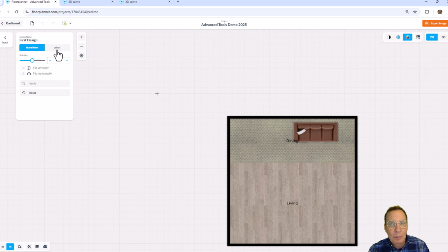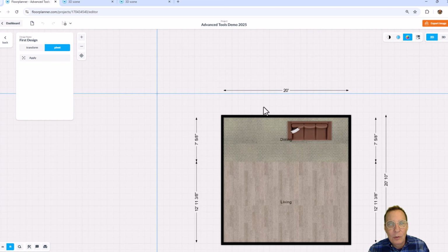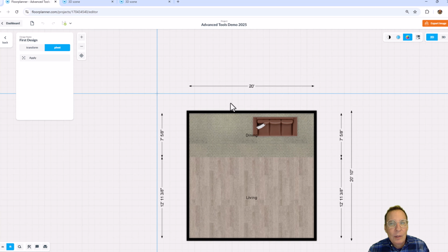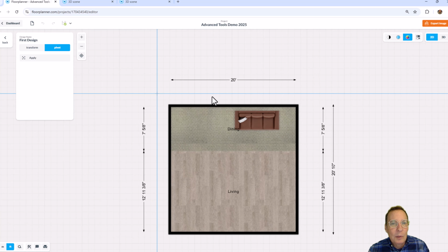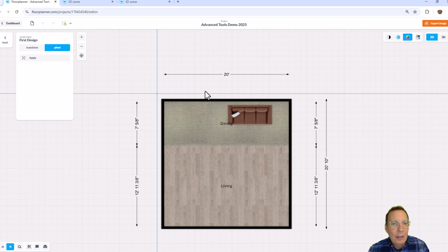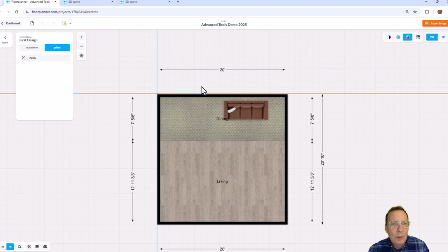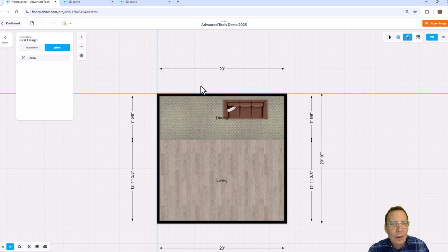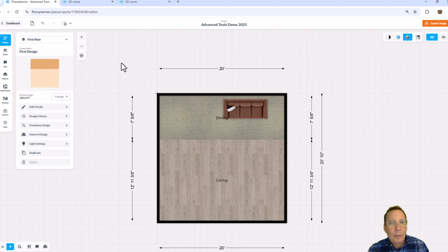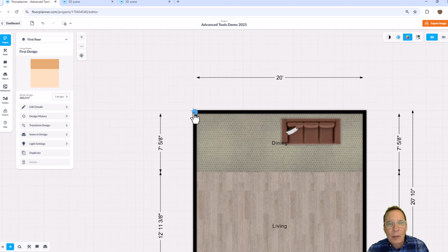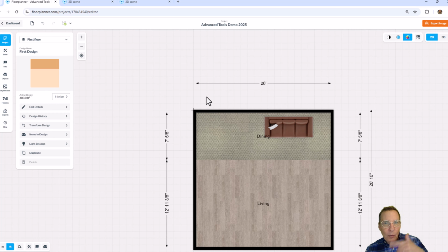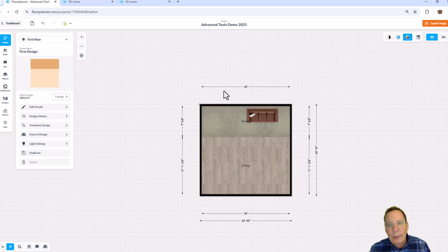What's really cool about this is that you can move the entire image and furnishings and everything to get that corner right up to the intersection of that known origin point, and let go and apply it. So we relocated it, so we've actually got that corner on that point. If I knew of the corner the same on the second floor, I technically could pivot on that same point. That's fine. It helps.